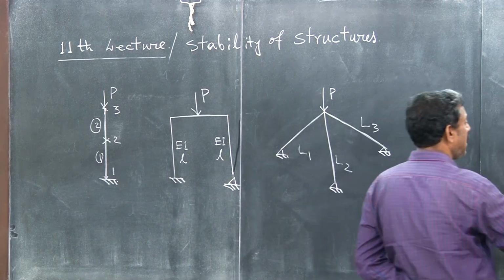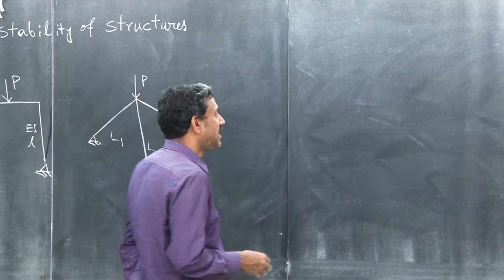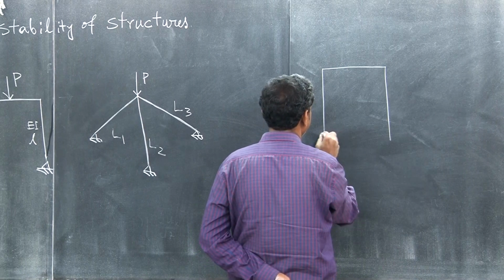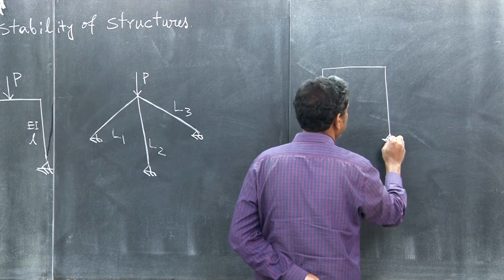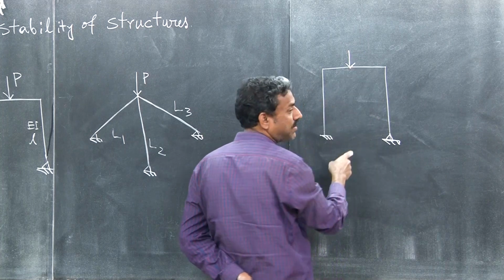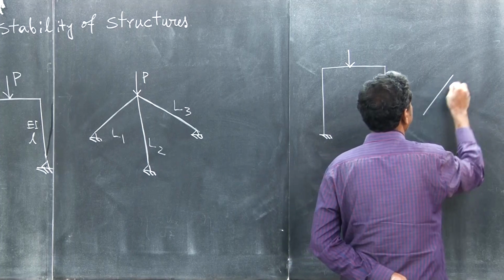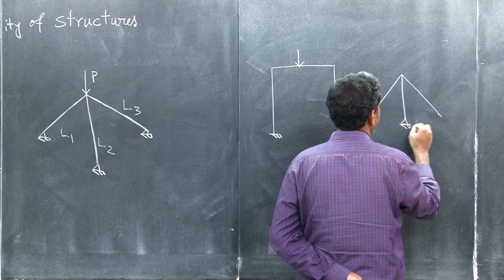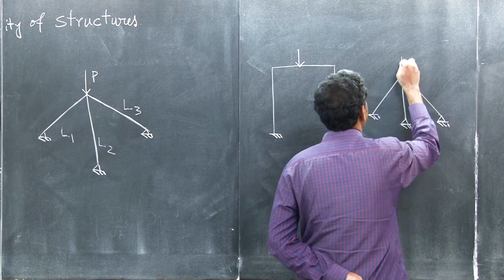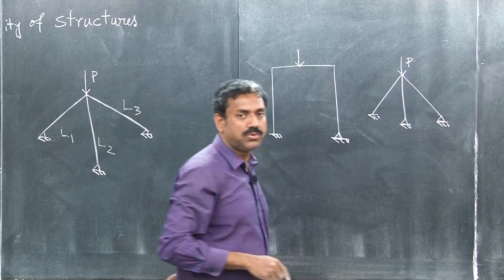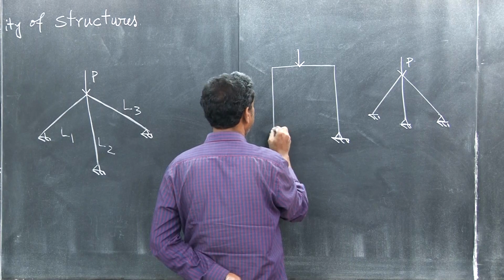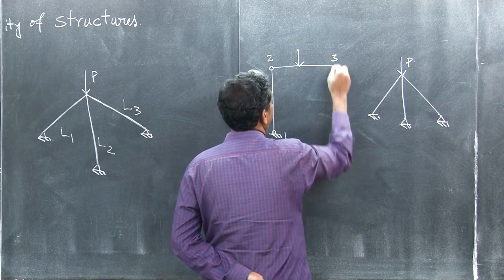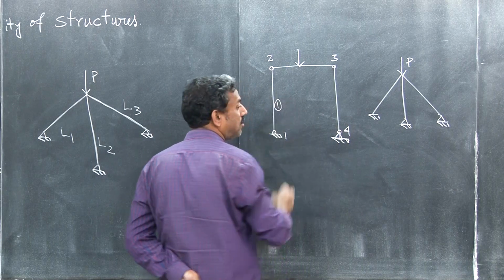So, as we see in any matrix method or finite element method, for example, you are having a frame structure, or some kind of structure, where these are all hinges, and it is subjected to some force P. The first thing to do is to discretize the structure. So, we define nodes here: node 1, node 2, node 3, node 4, and then there is global nodal connectivity.